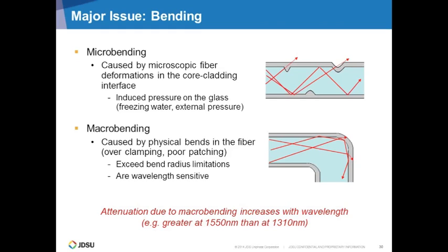Microbends are a little bit more common because in the past people would zip tie those cables, so that would change that fiber. One of the contractors showed me a picture the other day where the fiber was positioned in such a way that when he closes the patch panel, it would push on the fiber and bend the radius so that the fiber would not perform properly.